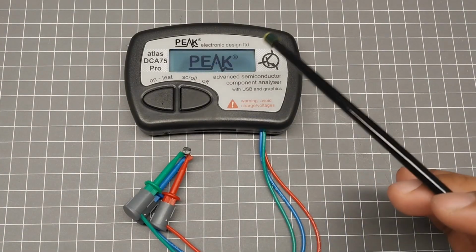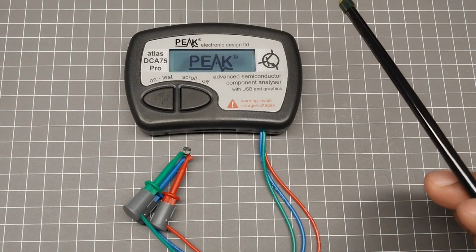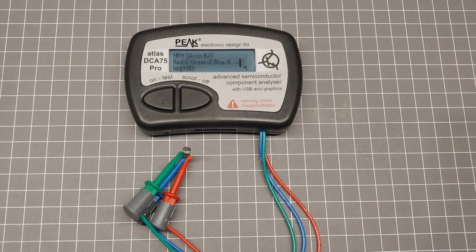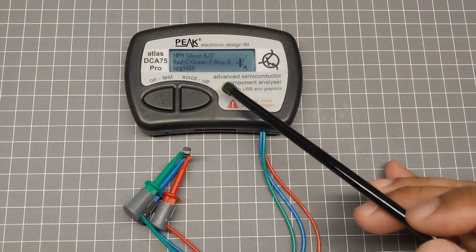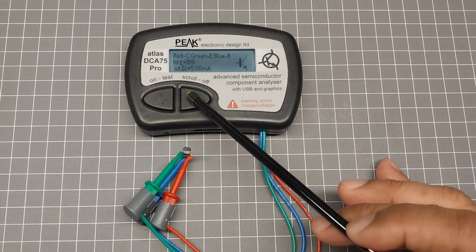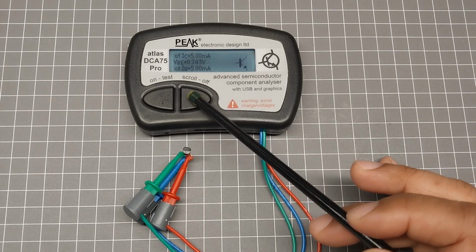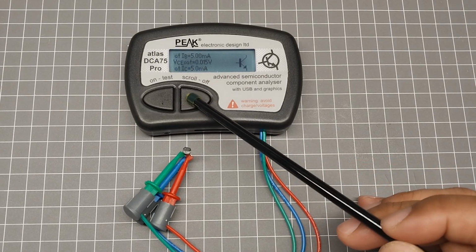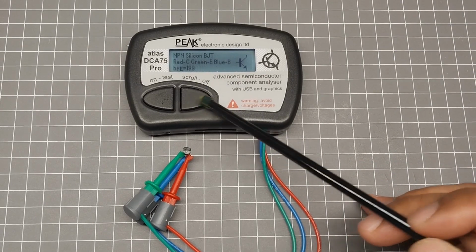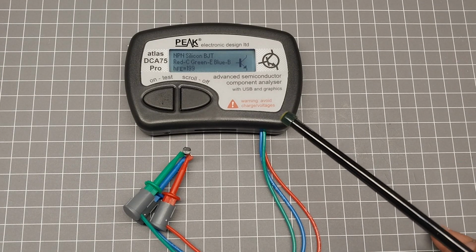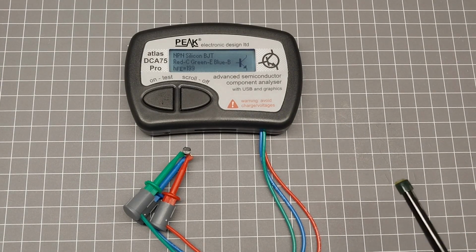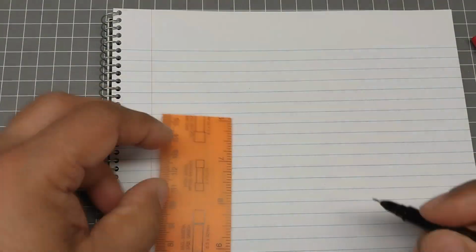So here I'm using a genuine BC337 NPN transistor, and on the datasheet it says the maximum collector voltage is 45. The HFE is also 200, collector current is 0.8 amps or 800 milliamps. So here we have 199. So the base emitter voltage is 0.743. So this is the only transistor that I can get closer to 100 beta. So we'll use this one for our demonstration purpose today. Okay, let me draw the schematic.